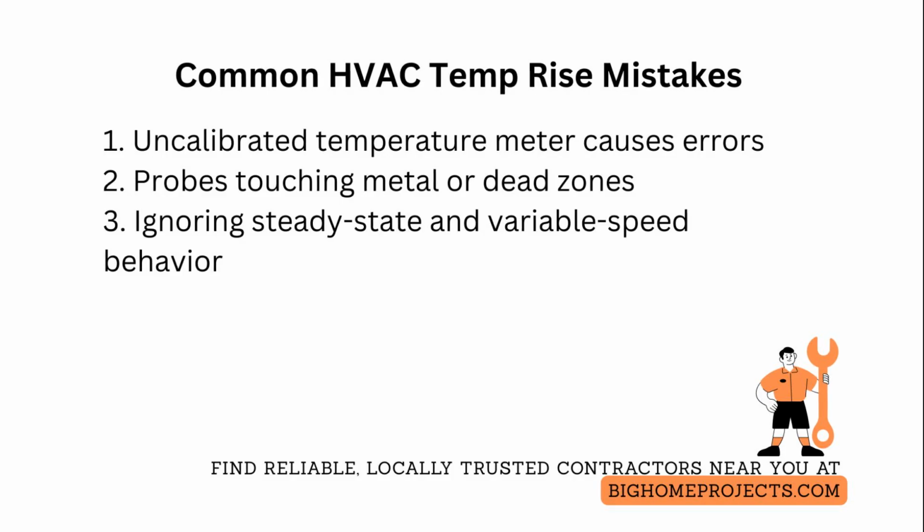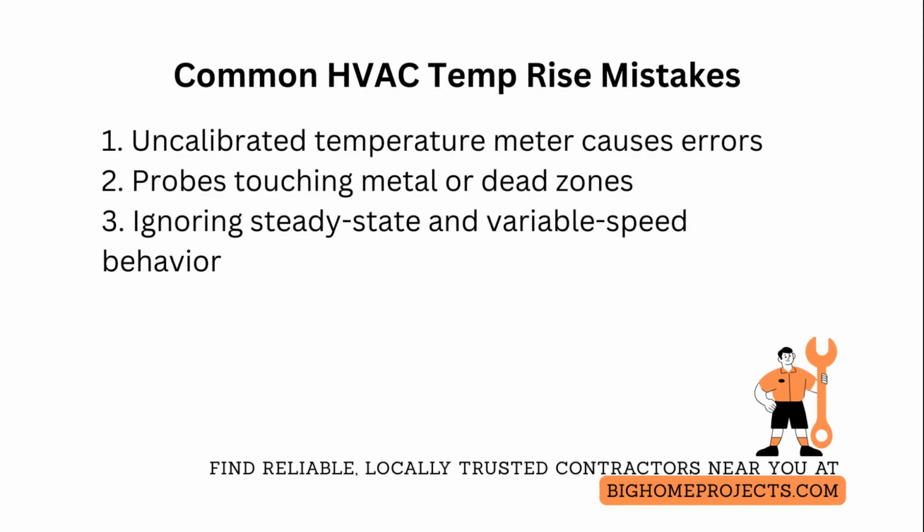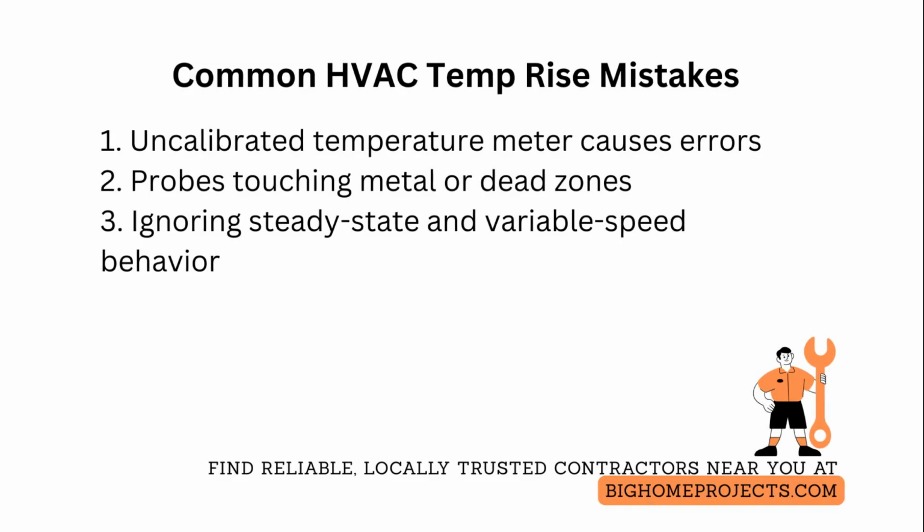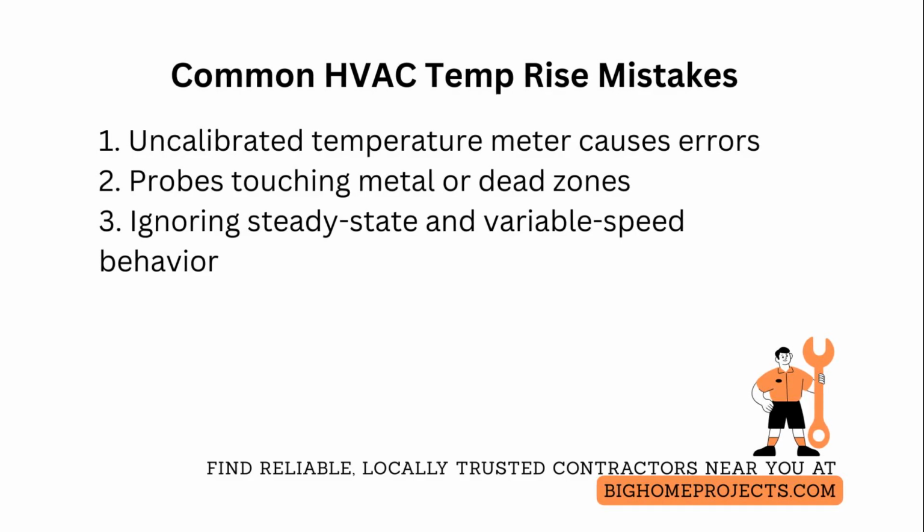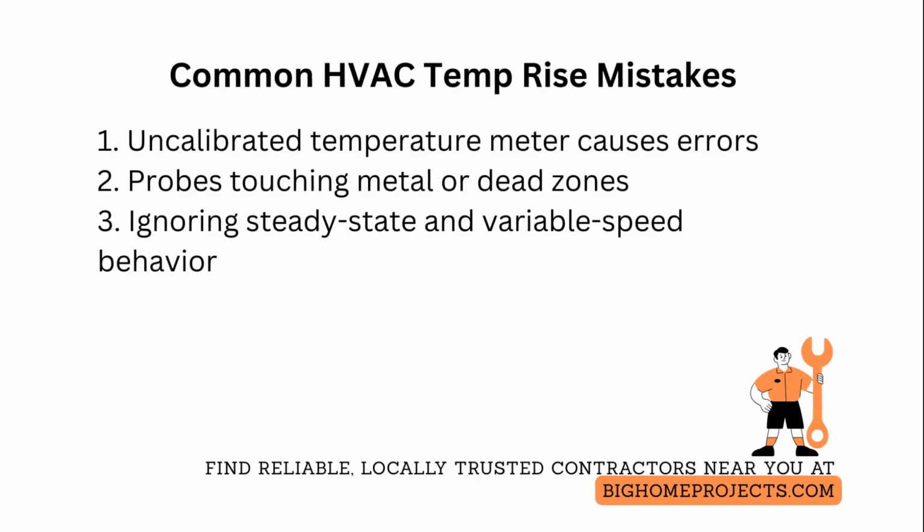The third of the top 3 is ignoring steady-state conditions or variable speed blower behavior, leading to inconsistent readings. Fix this by running the system until temperature and static pressure stabilize, verifying blower speed with a tachometer, and recording conditions so repeats are comparable.